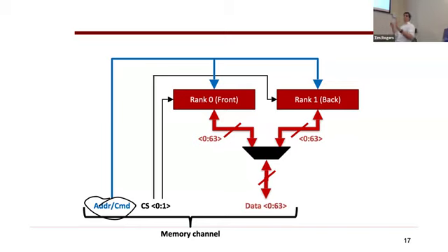And this is temporally shared. So unlike an SRAM where you can read the row and column all in one cycle, for DRAM, you'd open up a row and that would be one address, and then you'd send the column address. So DRAMs have these things associated with them called RAS and CAS, row address strobe and column address strobe. You've probably heard of these. That's because you have to strobe it or send it the row, and then it takes some time for that to become active, and then you have to strobe it and send it the column. And each of these has timing characteristics, in terms of nanoseconds.